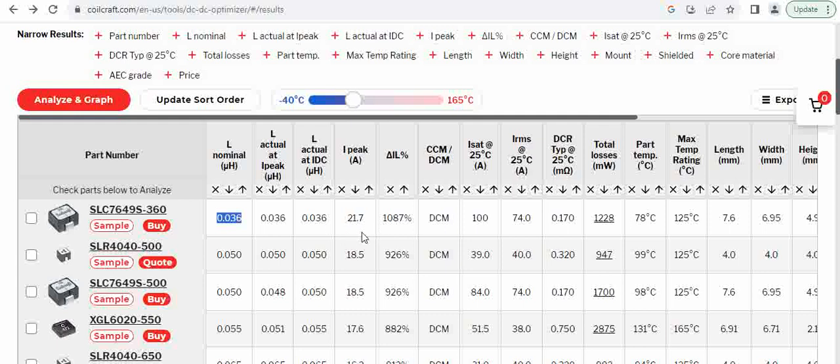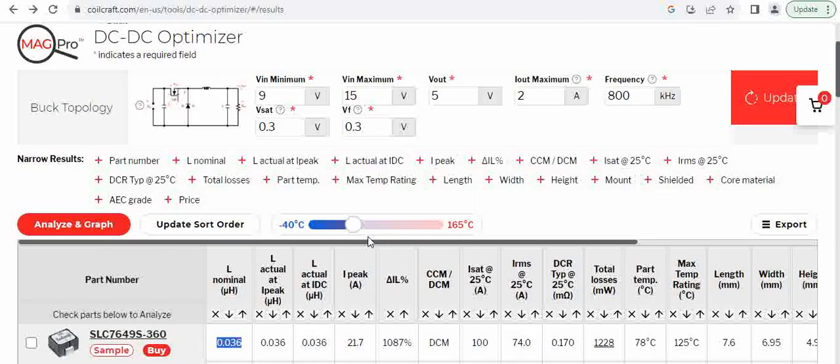Using this tool, rather than doing theoretical calculations, is useful. Generally when we design a buck converter, designers do calculations in Excel, getting all the formulas from the datasheet and trying to calculate the inductor, and then selecting an inductor is again a big problem. When we select the inductor, we select the one provided as a recommendation in the datasheet.